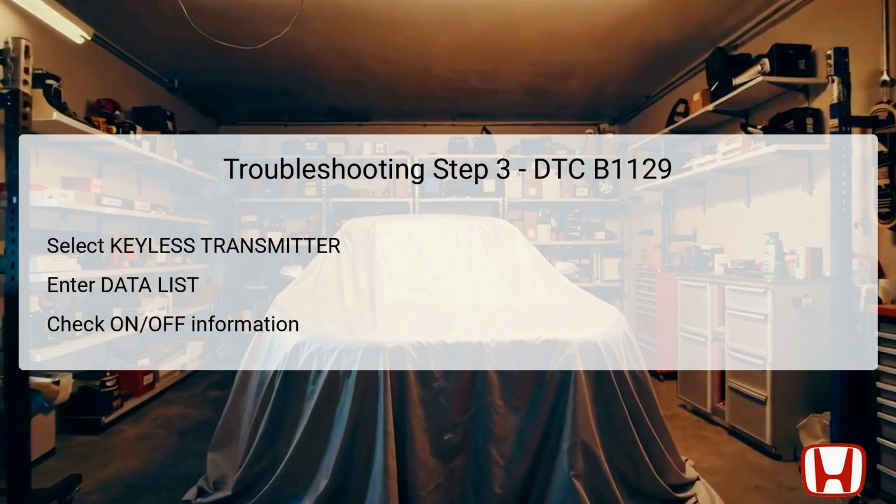It is essential to verify that when the switch is in the lock position, the indicator for the lock is on, while the unlock indicator is off. Conversely, when the switch is in the unlock position, the lock indicator should be off and the unlock indicator on. This data check helps confirm the functionality of the driver's door lock knob switch and its communication with the MICU.